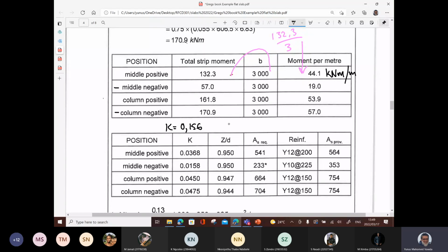Why do I need to consider that one with 20% redistribution? Because of the table. Correct, I heard somebody saying the table. So what thing in the table is where they've done the 20% redistribution? The hogging moments. Okay. 0.132. That's the one. Thank you.